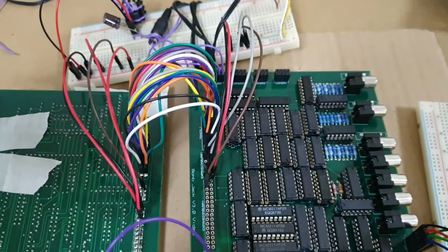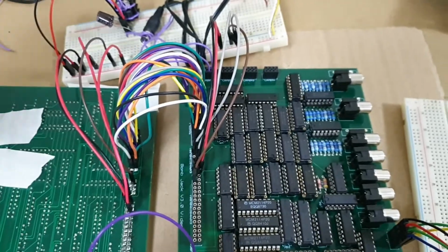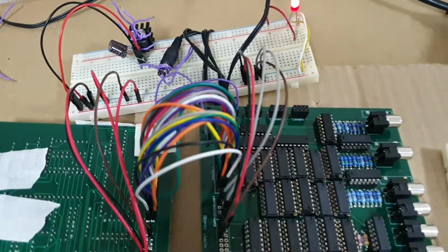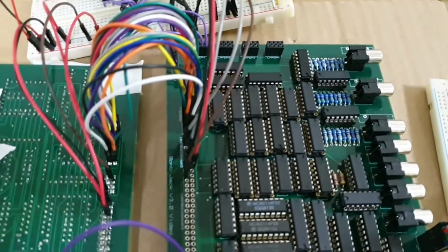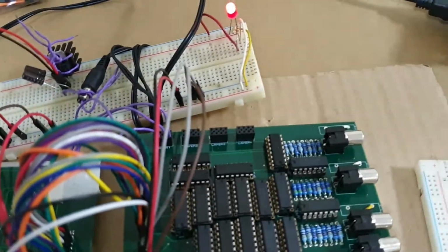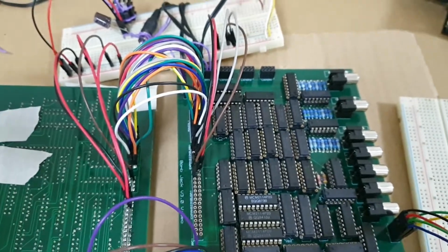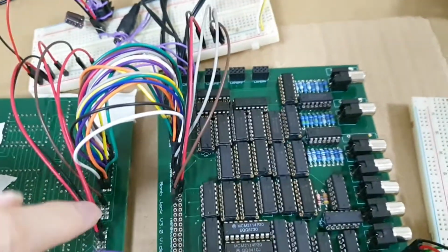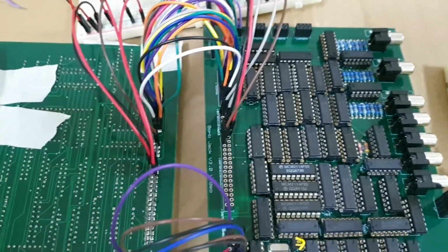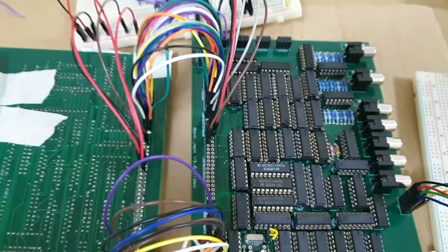So I decided that for all of the important signals where it needs to be definitely low or definitely high, for the low ones it's obviously connected to the board, but also now for the high ones. Memory enable right, which is this one, and this one here, have now been explicitly set to be high. I definitely do not want any spurious memory writes to be happening. Likewise for the extended memory bus lines, I've tied them definitely low. I've not left them floating or anything like that.